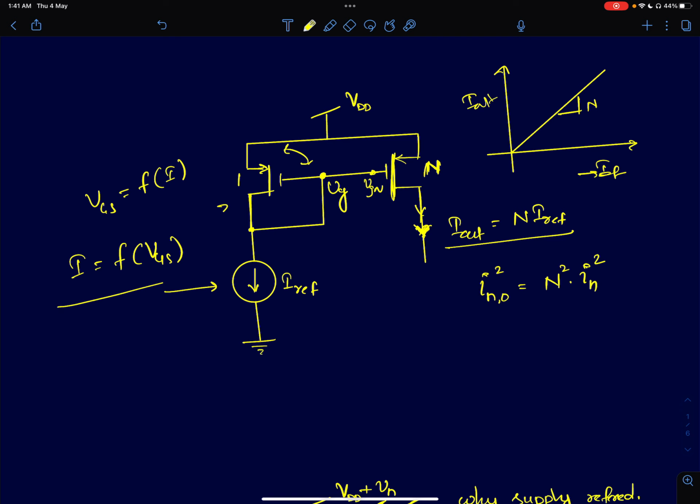Now first, the current to voltage generation is a nonlinear operation. But when you apply the same voltage to a mirroring device, it does an inverse nonlinear operation, and the output current then happens to be a scaled version of the input current. So that's why, even though these two devices are nonlinear, the output DC current and the input current are linearly related. Such systems, we used to call translinear circuits, or externally linear and internally nonlinear systems.